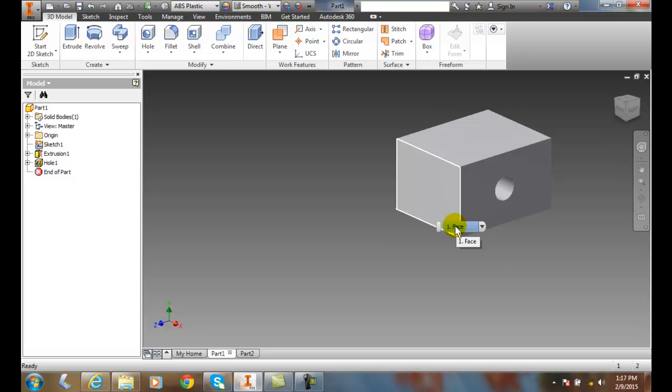We also have horizontal constraints and vertical constraints. We can say two holes are equal to each other in its constraints, so when we change one, it changes the other. We can say it's symmetric about a particular edge. We can have two holes symmetrical. We can have something fixed. All these are based on its geometry, so that's why they're called geometric constraints.